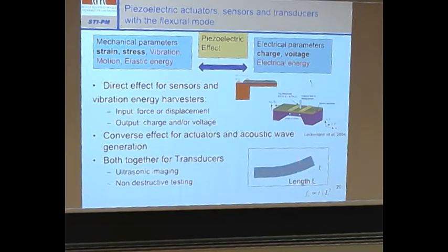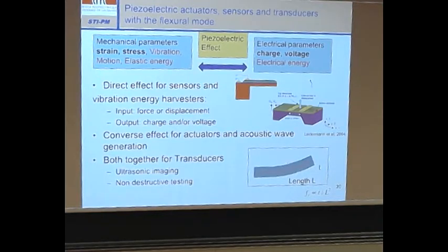The frequency of a cantilever's basic mode is about the thickness divided by the length squared. So you can tailor your system with mostly the passive, elastic part, and PZT or the other piezoelectric film will just modify this frequency behavior somewhat.